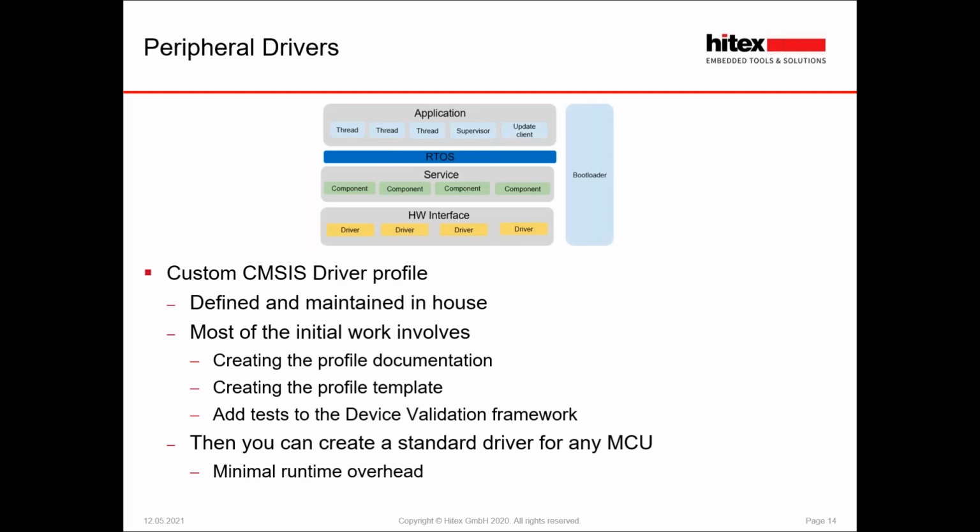One of the problems that we have for our overall architecture is that the CMSIS driver profile doesn't cover a lot of the on-chip peripherals, things like ADCs and timers and DACs, etc. Here we can create our own custom driver profile. It's up to us how we design it, but we can follow the CMSIS driver framework to keep that style. And we can also add tests to the validation framework so that we can bring up and test our driver.